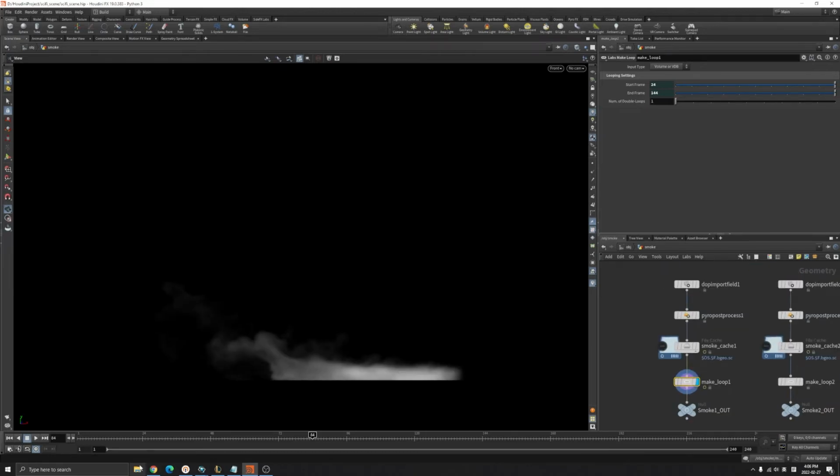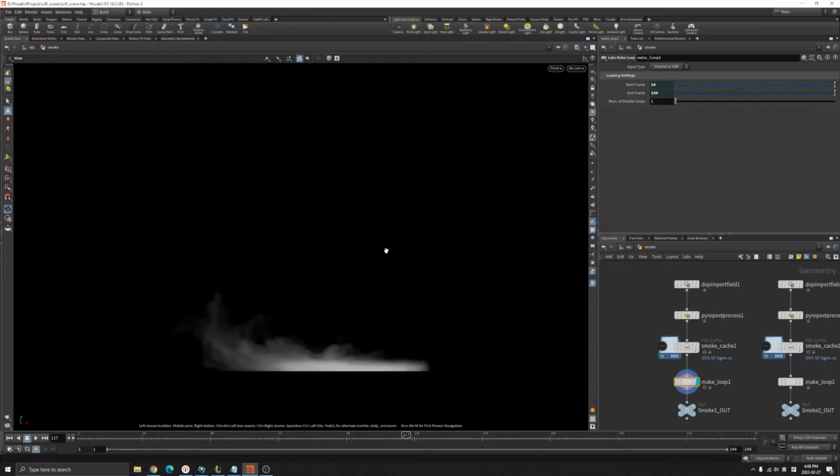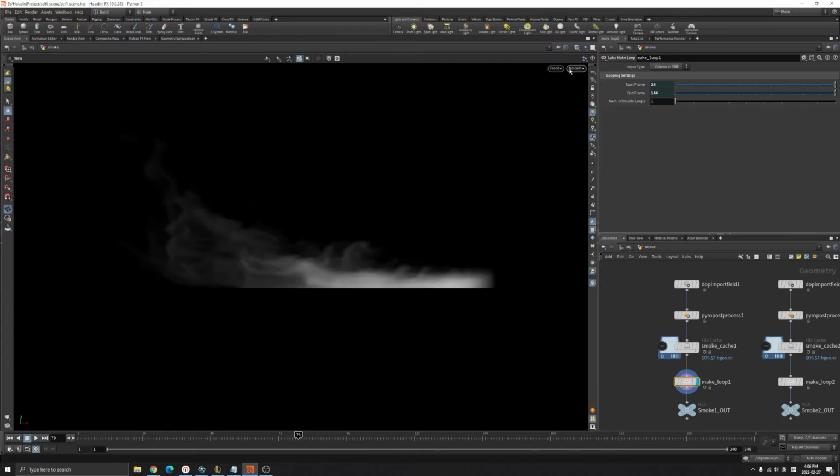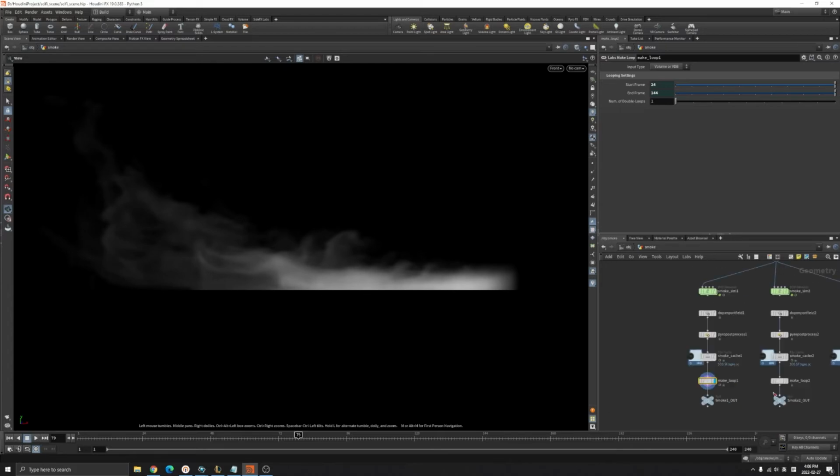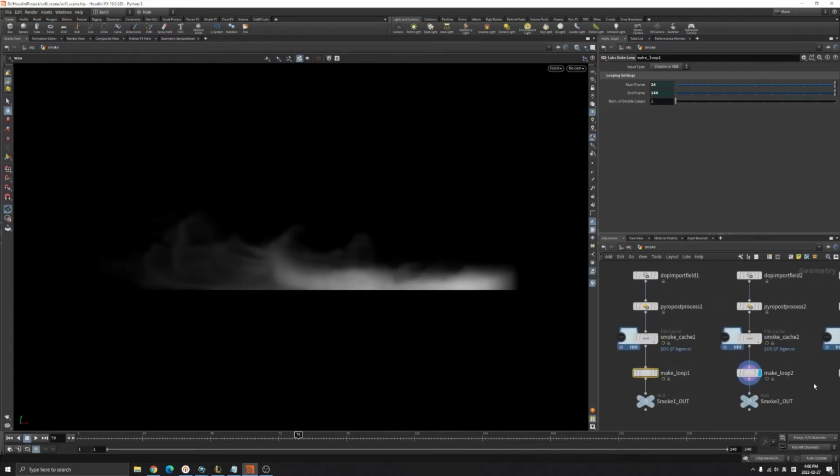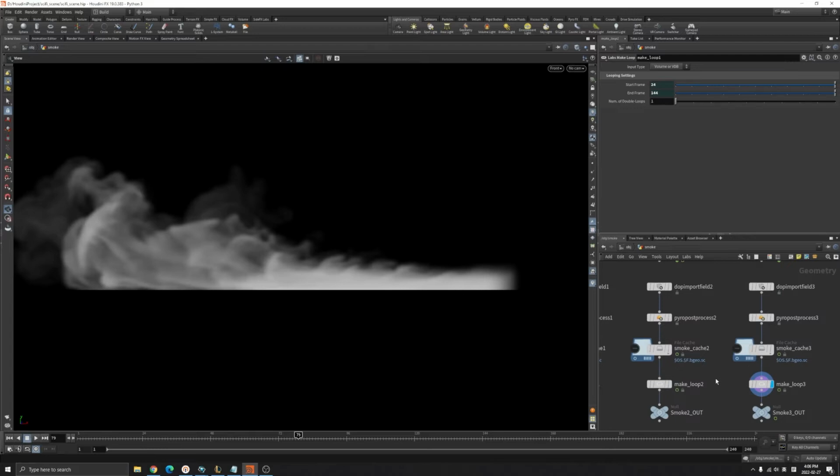You need to be in the front view so that in a real-time engine we can use it. Otherwise, in the perspective view, it's not exactly the front. So you need to get into your front view and control left click on your camera and then render it out. Okay, for 3 of them, but you can only use 1.